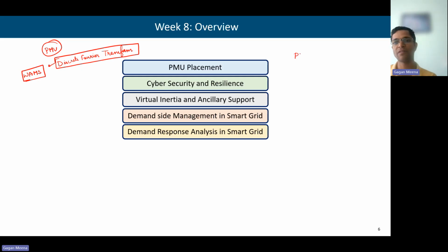And we also discussed different types of techniques for doing this phasor estimation, which is essential to the output, or the work, of the PMU. One we did was full cycle DFT. We also discussed half cycle DFT. Then we discussed cosine transform and sine transform also.